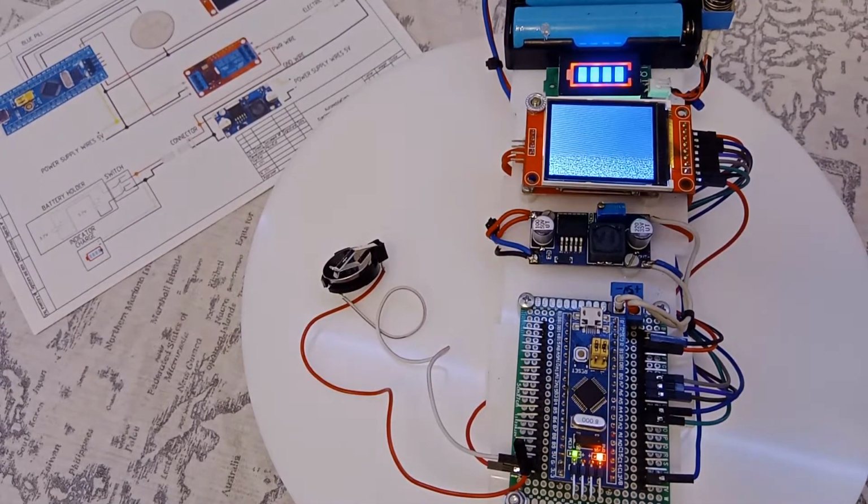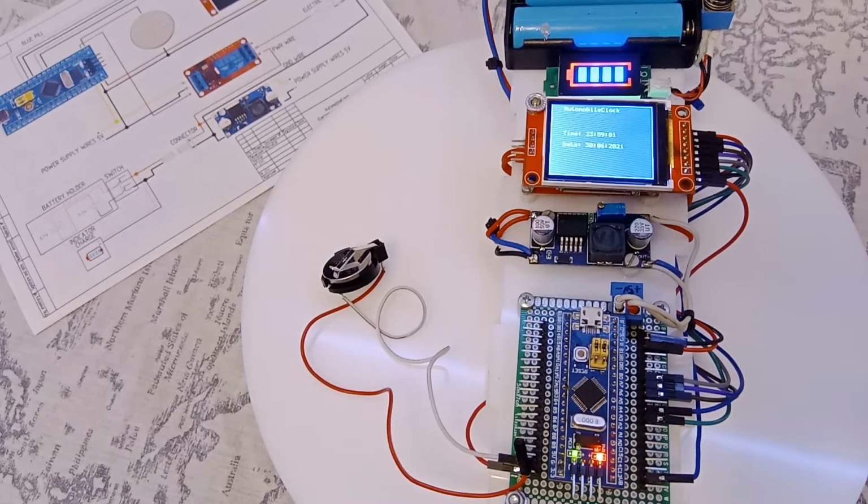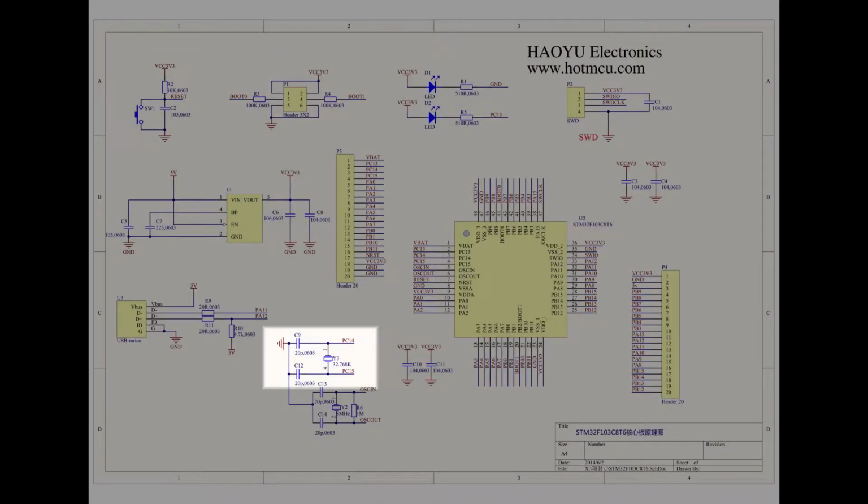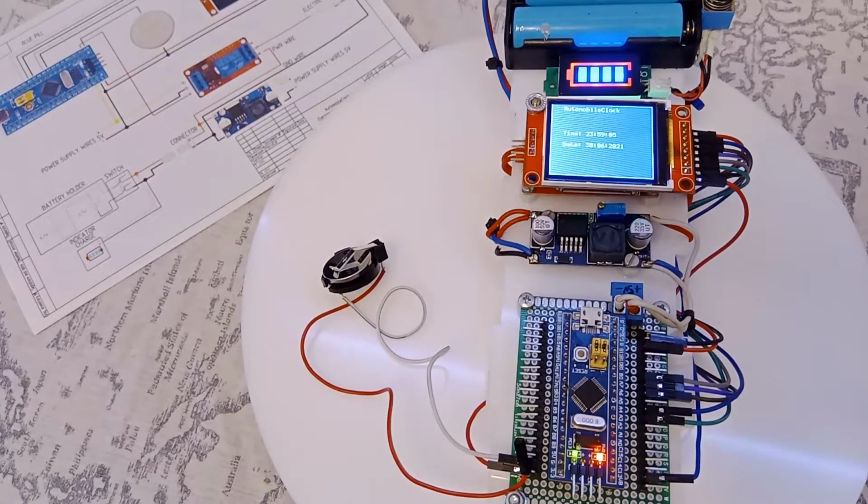When working with RTC, the controller loading can be delayed by a second. If you have problems with the 32 kHz crystal resonator or the capacitors C9, C12, the controller may freeze. The battery is now disconnected.